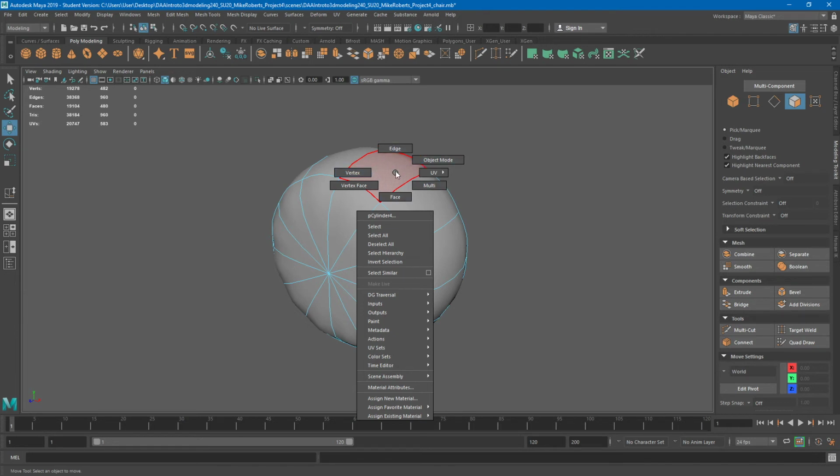Now, some of you guys have had that bright green material problem, right? That's because occasionally certain modeling functions, and it's kind of unpredictable, pop up here and there. No real way to predict it. Basically, sometimes you'll have a green wireframe. Sometimes you'll actually even have it where you can't get out of wireframe mode. And often, particularly if it's the bright green polygons, it's gotten confused about the materials, right? So if you hold down the right mouse button, like you're going to select, you'll see there's this whole other menu system down here. And we're actually going to see this a lot more on Project 5. You can assign an existing material. It's the very bottom one, Lambert 1, and that'll assign that gray material. That's everything that's Lambert 1.